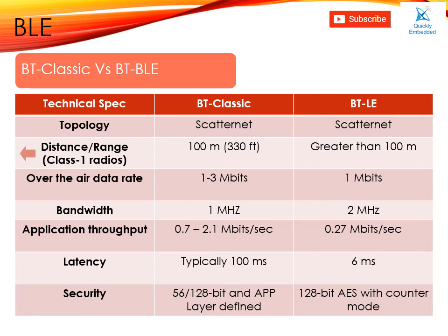Let's compare the distance and the range. When developing a Bluetooth device, you can give your device a better range by selecting a Bluetooth chip with the best receiver sensitivity and output power, and making sure that you use a good antenna. You're likely to run into a situation where you want to handle hundreds or even thousands of Bluetooth devices in a relatively small area, such as an office building.